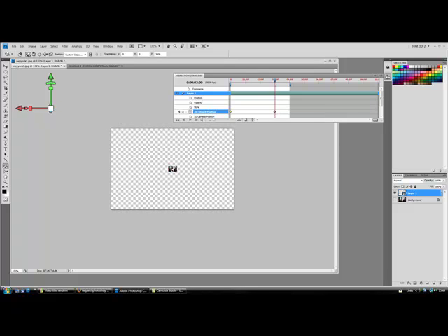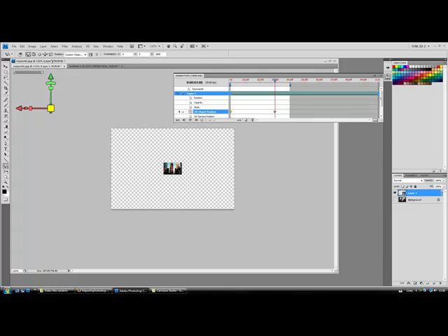Also, we want it to get larger as it's spinning, until it takes up the whole of the canvas. So we know that this first keyframe is this small. At this second keyframe, it's already spun 10 times. So now let's make it larger. Again, come to this widget. When the square at the center of the widget goes yellow, click, hold and drag up this time.